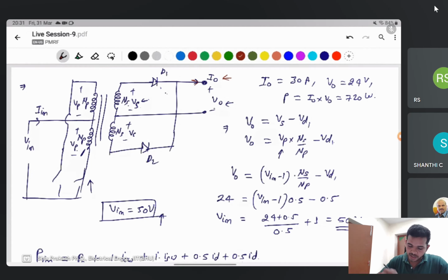All of these things, because the same flux locking phenomenon occurs in half bridge, full bridge, push pull. Yeah, the capacitor you use for the current control only, because of the leakage inductance that occurs in the transformer. That's why the capacitor is used to control the current only. Flux value will be reduced when the capacitor is used.